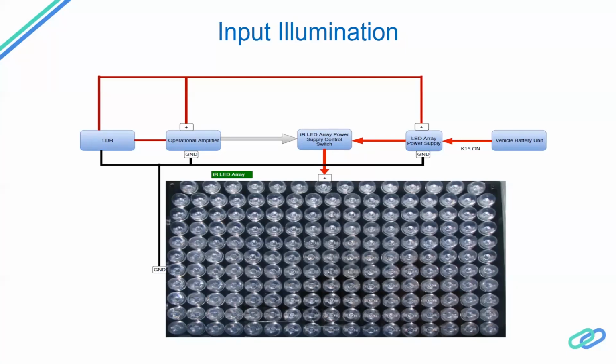So we have an LED array power supply that has a light dependent resistor, which will switch on the operational amplifier when the light goes below a particular level, so that even if it is dark, the camera should be able to capture the infrared illumination that is reflected from the driver's face and the objects around, so that it will be able to form the image of the driver, analyze the driver behavior and generate the necessary data that needs to be provided to the DMS ECU for analysis purposes.